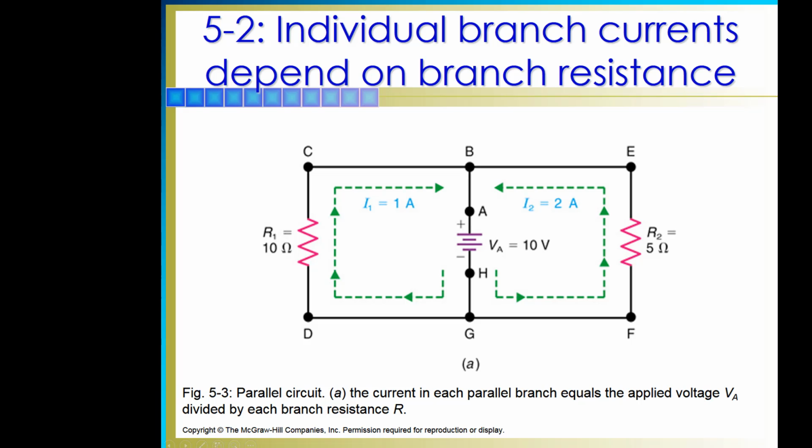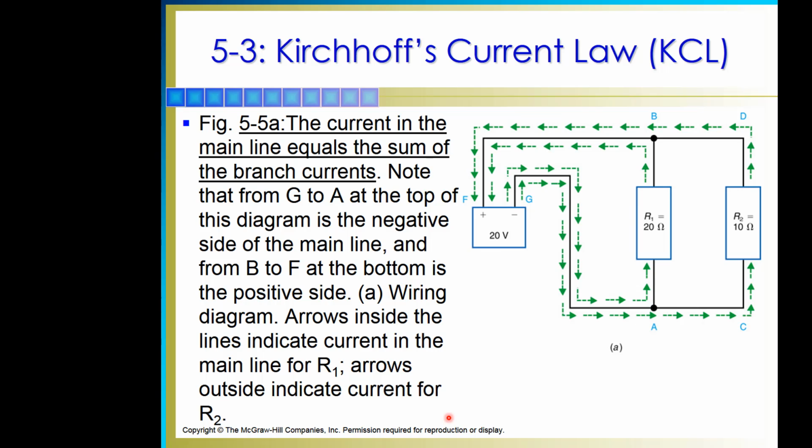Just a little bit more on the troubleshooting of parallel circuits. Remembering that those current values combine to the total current in our parallel circuit. Here we have 10 volts, 2 resistors in parallel. They're just drawn a little bit differently. Our 5 ohm resistor has 2 amps. Our 10 ohm resistor has 1 amp. These two are going to combine for a total of 3 amps.